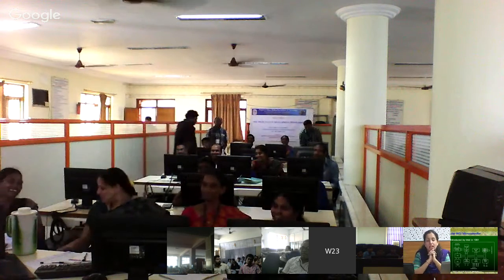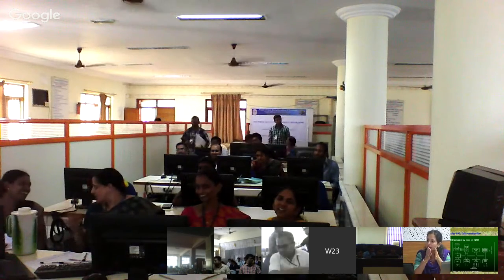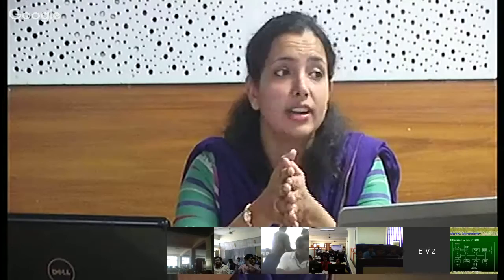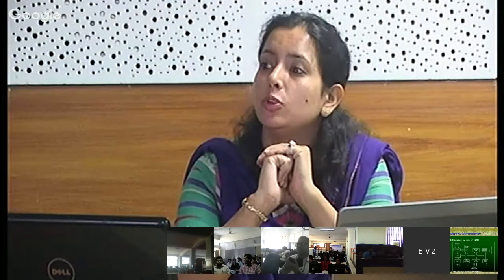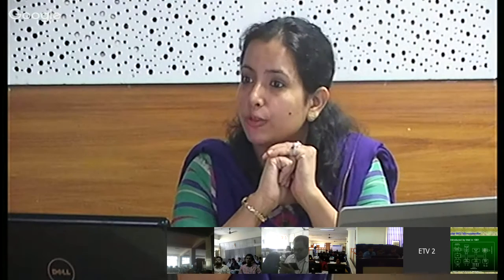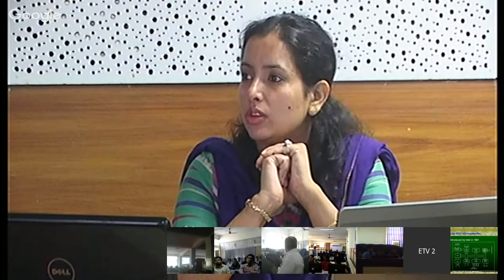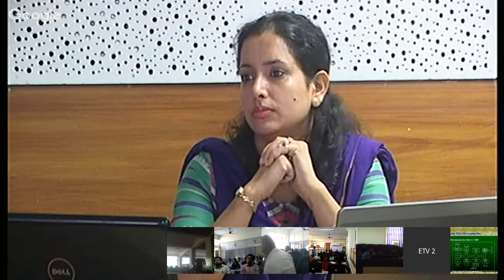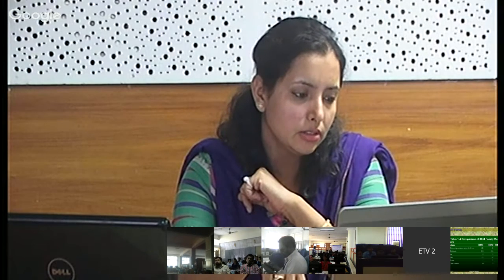That's also right. Whenever you want to do serial communication with the IBM PCs, you need to have baud rate compatibility. Baud rate compatibility is very important. And at this particular frequency, 11.0592 megahertz, the baud rate compatibility of the 8051 with the IBM PC is the best. So that is why this particular frequency is used. Okay, so that was about the oscillator circuit.